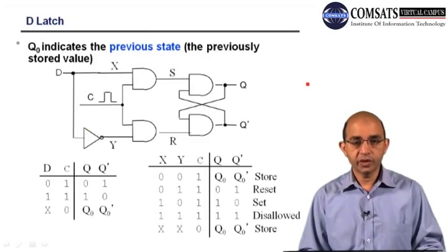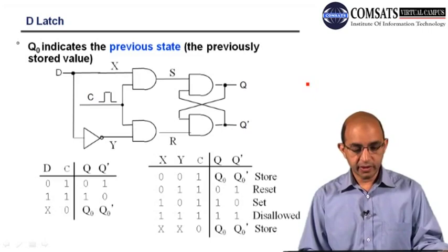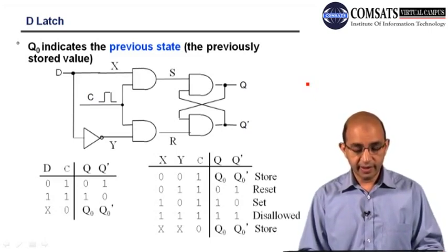So in order to overcome those different problems, we have introduced the D-latch. You can see that we have an SR latch over here. So we have the function table. Here we have X and Y, this is the control or clock, and Q bar. So what I did over here is I have inverted the second input.